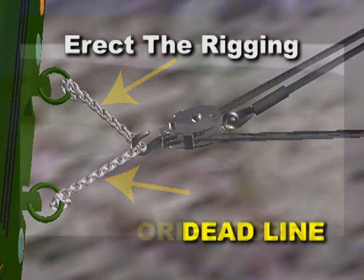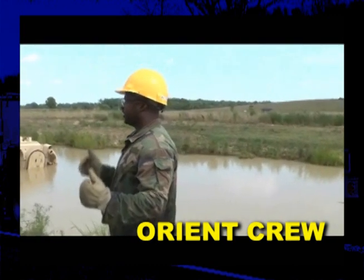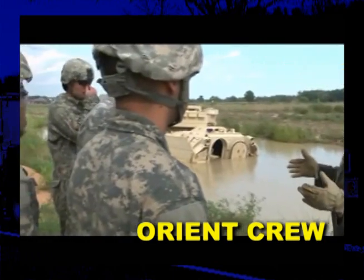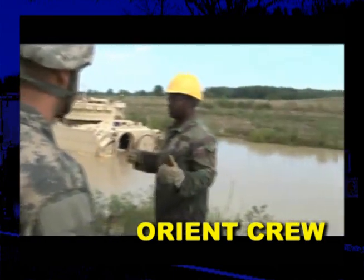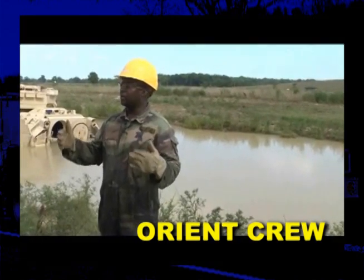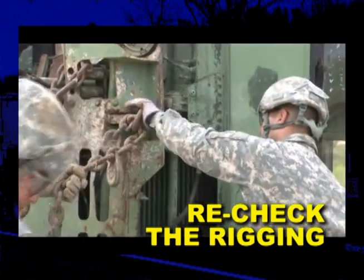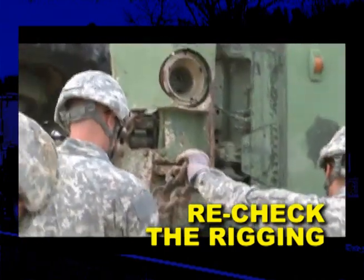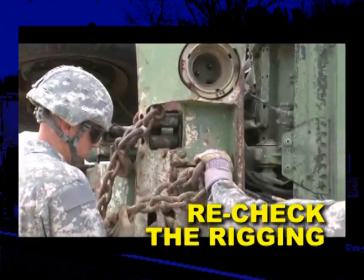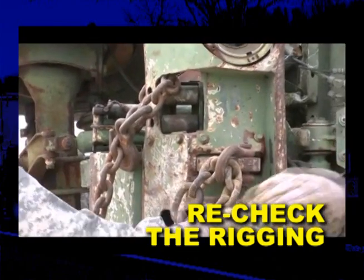Now that we are aware of the required rigging, we can orient our crew and begin connecting to the load. During the erect the rigging step, we should orient our crew and instruct them how to assemble the tackle. Work as a team and observe all safety precautions. The 7th step of recovery is recheck the rigging. During this phase of recovery, you must ensure the tackle is rigged for safe operation. Remove any slack from the lines and move everyone to a safe area.